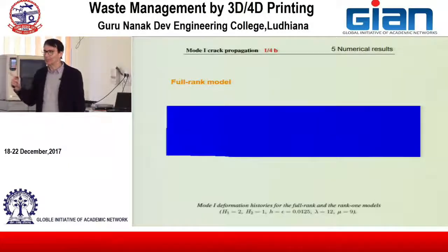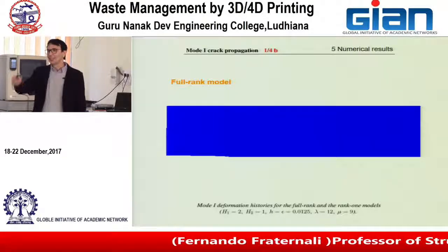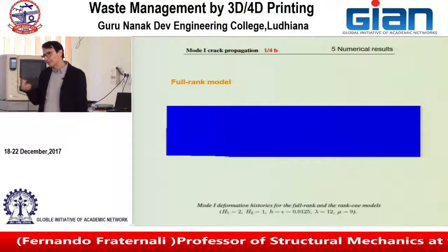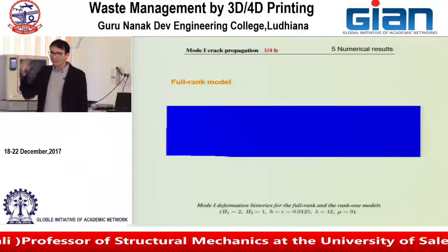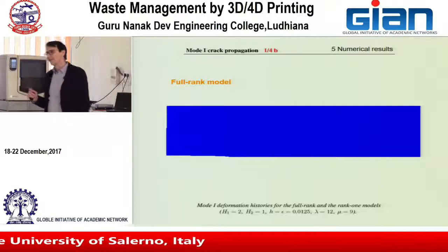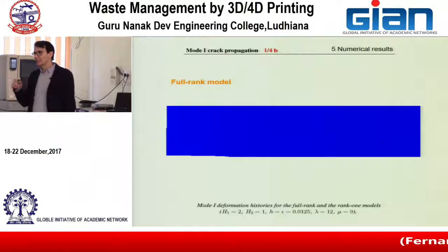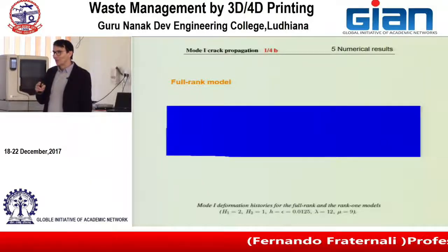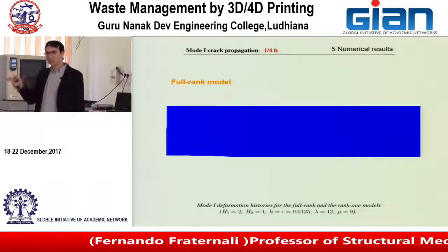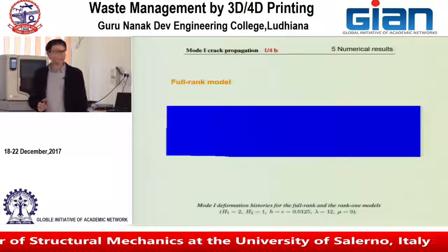If you don't use the epsilon neighborhood technique, your result will depend on the mesh that you have used. The epsilon neighborhood is an average. It can be seen in many, mathematically complicated ways. It is a kind of convolution technique or averaging technique in order to correct the mesh anisotropy that otherwise you will get with your prediction.